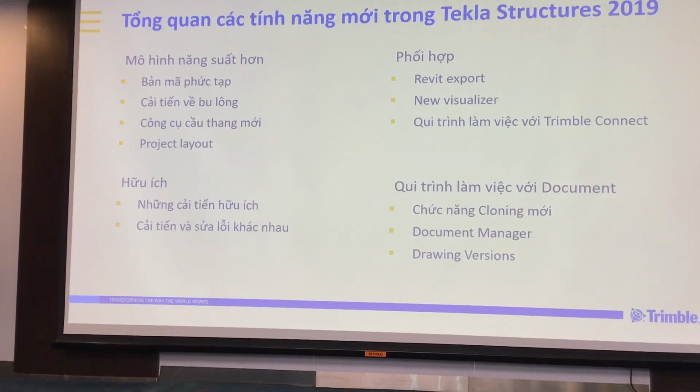Yes, definitely. Okay. Well, the new function of plate work with bent plate and unfold is very useful. However, how reliable and precise is the unfold dimension actually? How reliable and precise is the unfold? Very, very precise. And you've also got control. There's a file in the system where you can actually set how you'd like the unfolding rules. The unfolding is very nice and very precise and very accurate.